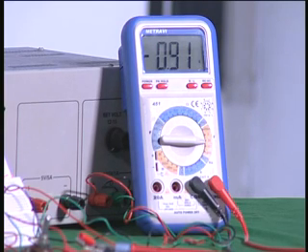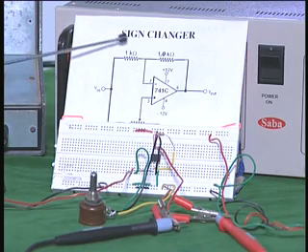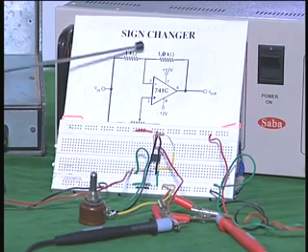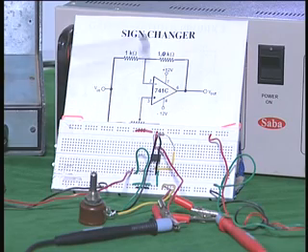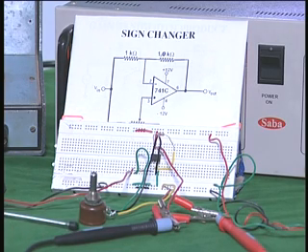Therefore, I have changed the gain continuously from +1 to -1 by changing the potentiometer from a 0 value to a maximum value. So, this is what we call a sign changer. You can change the sign of the amplifier by continuously varying this from -1 to +1 or +1 to -1 by using the potentiometer. So, this is again a very simple and useful circuit for applications.